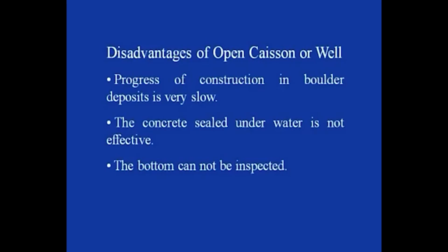The concrete seal is usually carried out under water and therefore it is not very effective. Another thing is the bottom of the well cannot be inspected. So these three are the main disadvantages of open caisson or well.